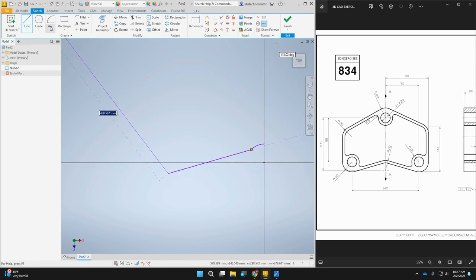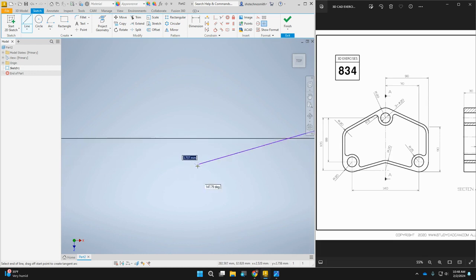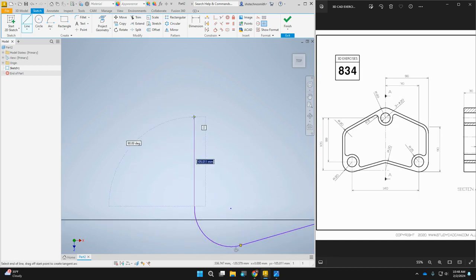I could go back through and use one of my commands here, but this is very common when we're drawing our shapes. Inventor has put in where you can, right now, the edge of or in between my crosshairs is yellow. If I put my mouse on the end, it turns gray. Then if I click and drag, it creates an arc. Now I'm going to go over here and up. When I come out, I have two choices: I can either be vertical or I can be tangent. It doesn't matter which one because I'm going to have to add the other later. So I'm just going to do the vertical one.